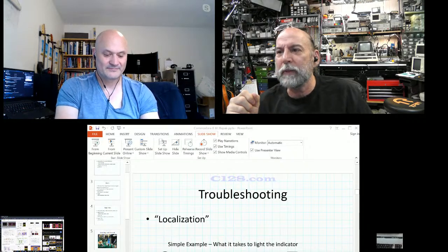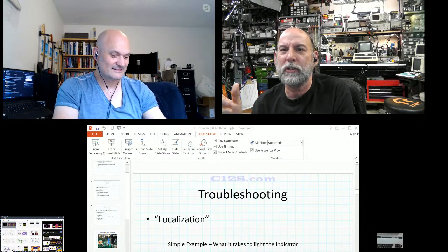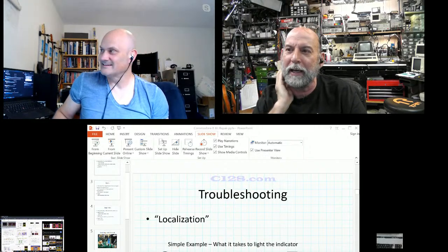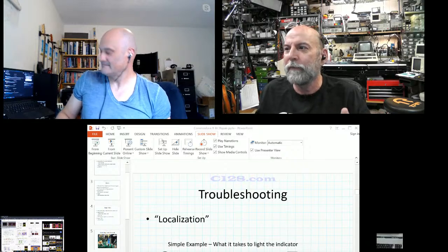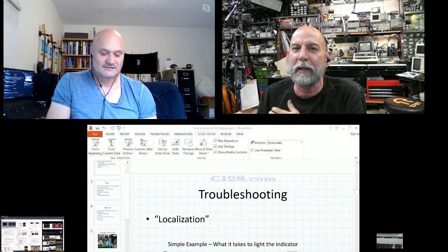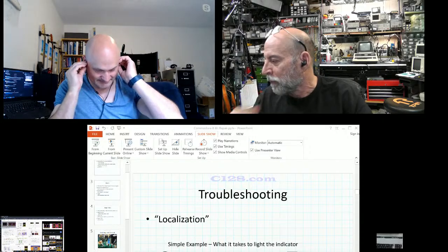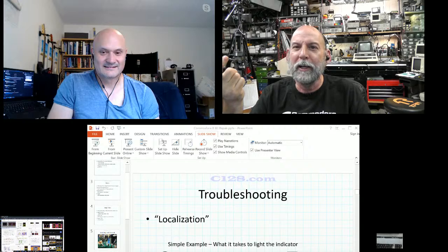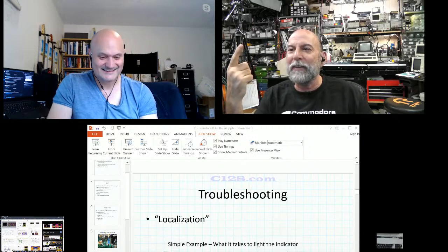Now I developed a technique because again, I was a street fixer in the old days. I used to go to Matter Park in Marion, Indiana, with the tackle box of parts. A lot of times just the audio outputs, because people were always shorting their outputs together in their 8-tracks. Remember 8-tracks? They would pop their outputs. So I would use my finger as a test point. And if you put it right on the recording head, or right up inside where your needle on your record player is, if you've ever touched those wires, you hear this loud pom. Well, guess what? That's a valid test point.